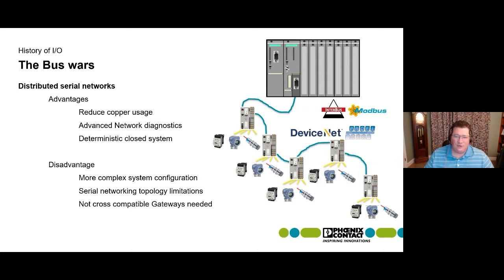It made it easier to work with and easier to troubleshoot because these I/O devices can now contain some base diagnostics and are able to diagnose what's going on at their individual stations, so that we're able to bring this diagnostics back into the system to provide a mechanism for the PLC to more easily diagnose problems at the individual I/O modules in the system. And then last, because this is a closed network, this was a deterministic network.